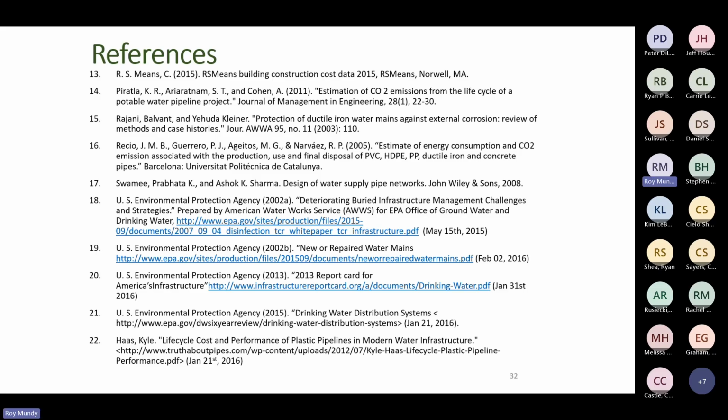The tuberculated pipe that many people see, and I'm sure many of you may have seen in water systems, wherein there was a significant decrease of diameter in the pipe because of tuberculation. Tuberculation does not occur if the pipe is cement lined. Now, how do I know that?